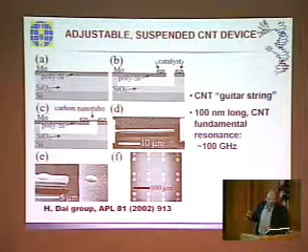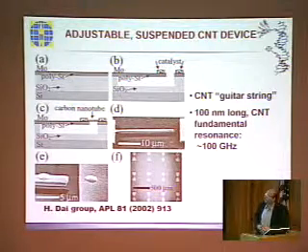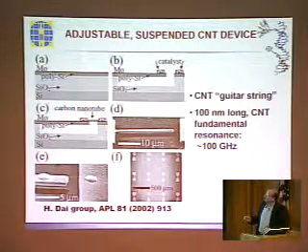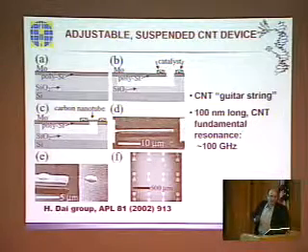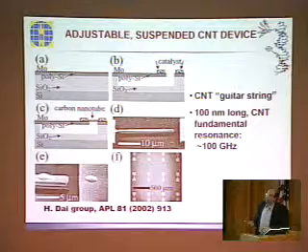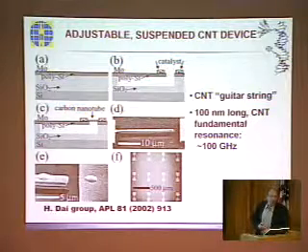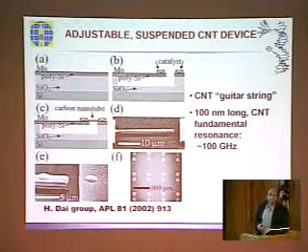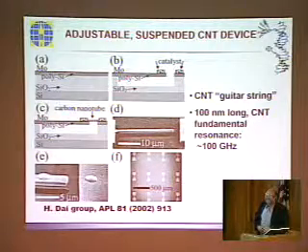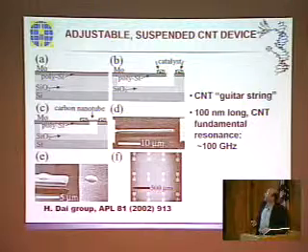These also are extremely sensitive to molecules bound to the surface. Other researchers have shown that you can decorate the carbon nanotubes with specific bonding sites that make the electrical resistance of a tube sensitive to the bonding of a particular antigen or a particular small molecule. So you can make very selective, ultra-high sensitivity sensors with carbon nanotubes. So there's all kinds of interesting applications that are being looked at.